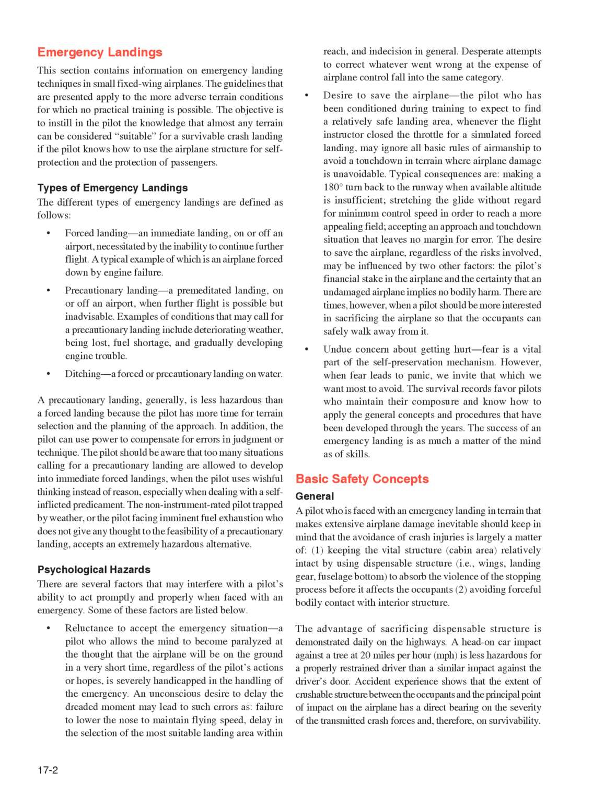In addition, the pilot can use power to compensate for errors in judgment or technique. The pilot should be aware that too many situations calling for a precautionary landing are allowed to develop into immediate forced landings, when the pilot uses wishful thinking instead of reason, especially when dealing with a self-inflicted predicament. The non-instrument rated pilot trapped by weather, or the pilot facing imminent fuel exhaustion who does not give any thought to the feasibility of a precautionary landing, accepts an extremely hazardous alternative.